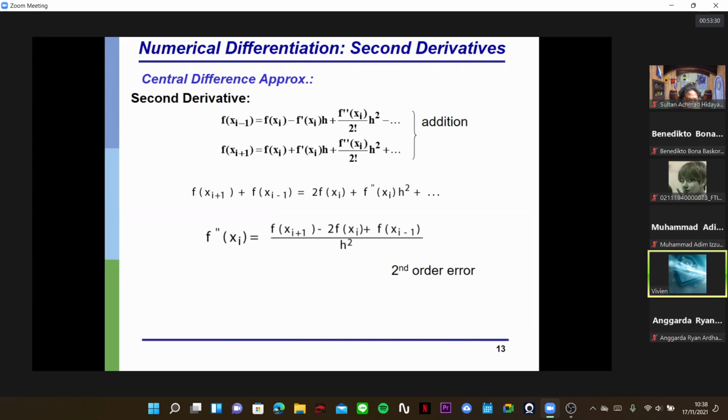If we want to insert this in, for example, MATLAB, we can insert this function as inline. We call the function inline, and we insert the equation in single quotation, 1 minus 2 times phi squared minus t, and then we insert the variables, the parameters, t and phi.